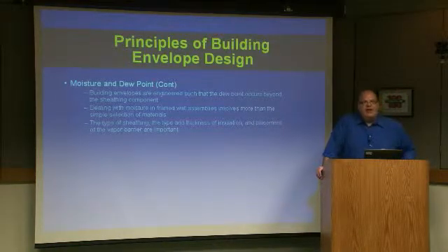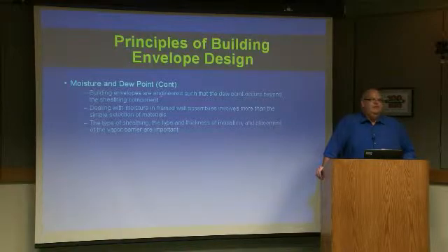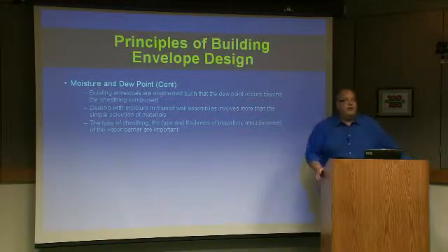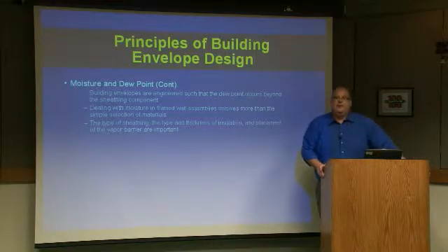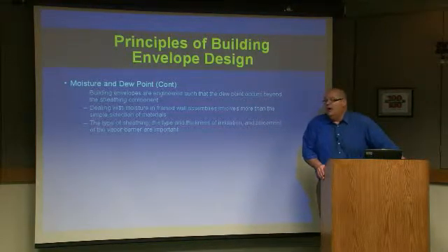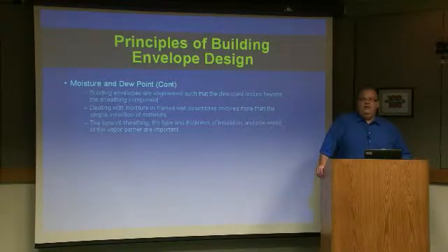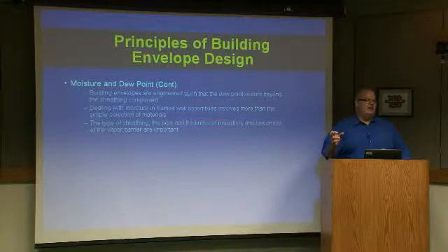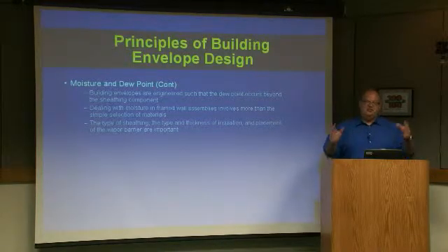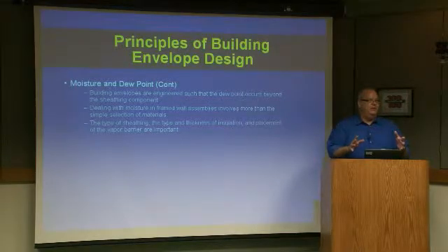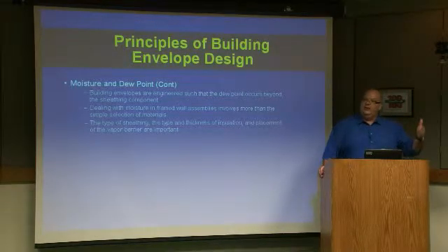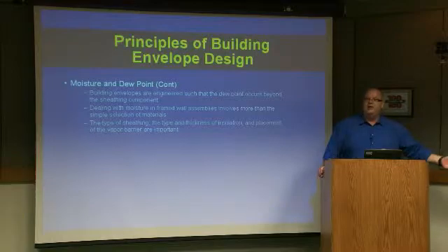There is a movement out there now. People talk about moving the dew point outside the wall. You have the Boston masonry wall, right? Very common out of Boston. We're seeing it up in the upper Midwest now, places like Chicago, where they're getting rid of all the cavity insulation from inside the framing. And they're taking 3 inches of extruded polystyrene and sticking it out in that brick cavity. So you've got the brick, you've got the air space, you've got 3 inches of extruded polystyrene board, then you've got your gypsum sheathing, then you've got your stud space and your drywall. No insulation between the studs.